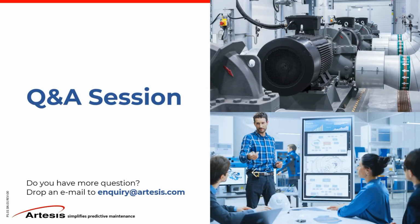So another question from Mark, are there any modifications to the MCC to be done before using the portable system? Yes and no. Actually, the short answer is no, because in order to use the portable system, you can just open your MCC panel and use the non-intrusive probes to start doing your test. But if you don't want to open your panel and do live motor testing, you can do so by installing the additional optional plugs that we're providing, which will then sit there permanently, and then you will just use a plug to connect to the MCC to make your live motor testing. So both options are there.